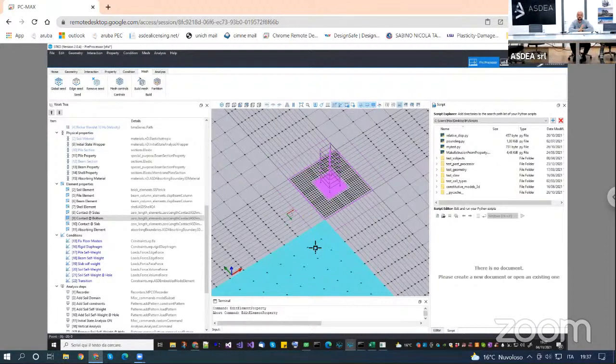I prepared the code for doing that, because I was aware of this problem. And yes, for sure, when you make the inner solid nonlinear, the absorbing boundary will not work properly if you leave them as they are. But in the OpenSees code, I allowed the update of the G and Poisson ratio of the absorbing boundary. So in the future, I will show another webinar where we can update at the end of each step the shear modulus and Poisson ratio of the absorbing boundary to match those of the nonlinear material.